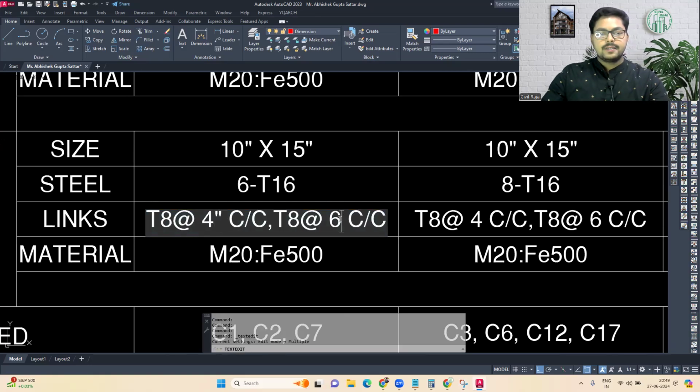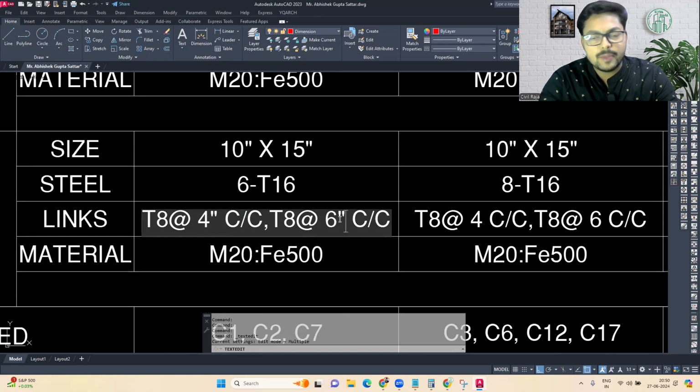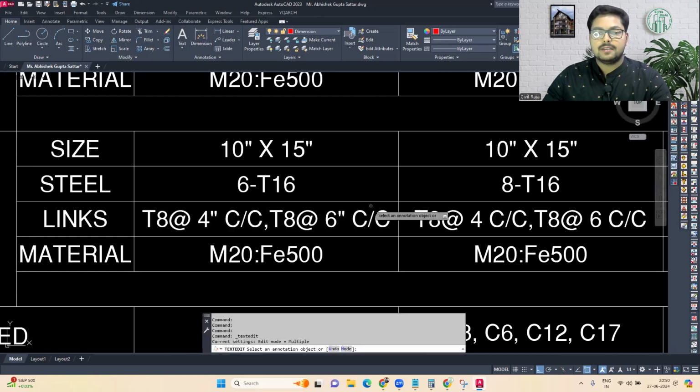Now in the middle portion, we have to provide the same dia of bar as the tie, but the spacing will be increased, because in the column we have higher moments at the ends and not in the center. So we have to make our ends stronger. That's why the rings or ties are placed closely at the ends, and at adequate distance in the center part.